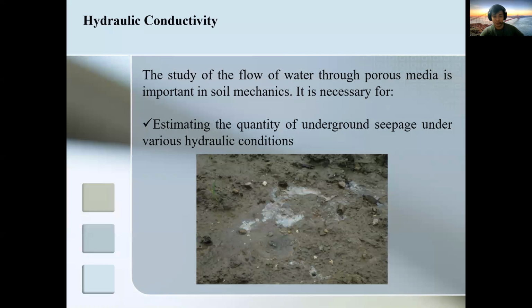And of course, if you have that kind of condition in your site, you need appropriate measures or a different approach in establishing your foundation layout. It could be a mat foundation, so your building is like a boat, right? It lies on the water, floating on the water. Or of course you could apply a deep foundation, so that it establishes its foundation on the bedrock. So those are usually the problems.